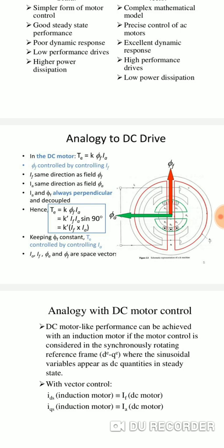Now coming to the AC motor, we are giving just one supply, that is a three-phase AC supply to the stator side, and we have these two quantities in this three-phase AC supply only. These two are combined: the component which is responsible for the torque as well as the component which is responsible for the flux. These two are mixed together, and that is given to the stator of the induction motor. And now we have to separate these two quantities. In this three phase only, both the components are there.